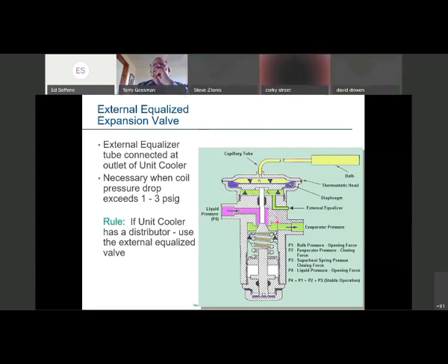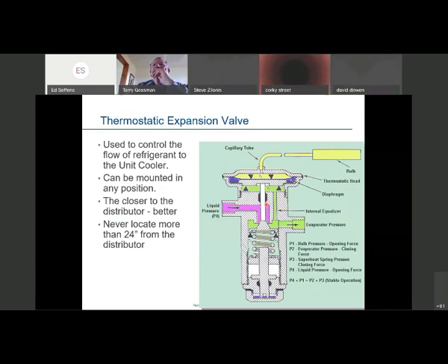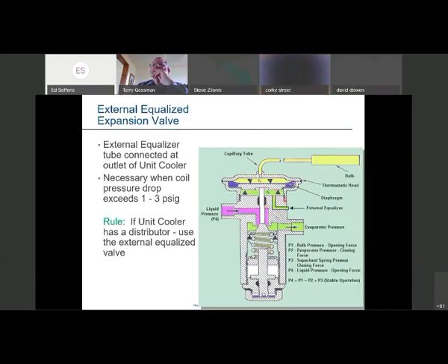Again, I always say replace like for like if you can. If you have an expansion valve that is internal equalized, you can replace it with an external equalized expansion valve. If you have a balance ported expansion valve, make sure you replace that valve with balance ported and not a conventional expansion valve. There's a reason for that. We don't really talk too much about power heads, the charge in the power head, and the element and everything. We don't talk about that too much here.